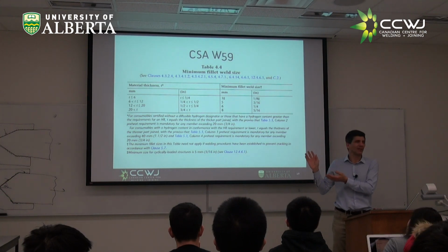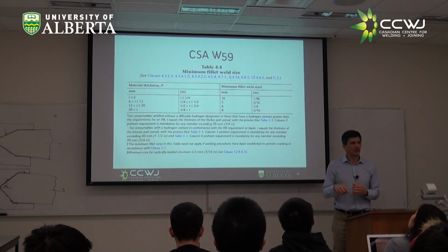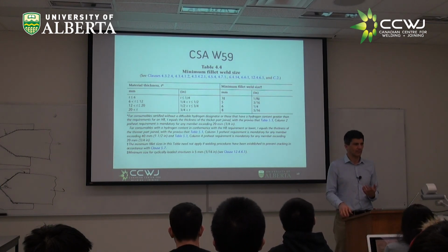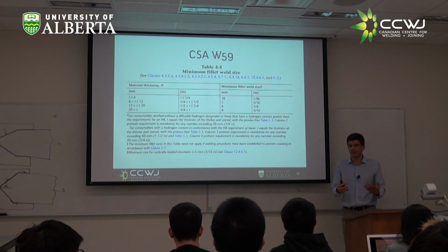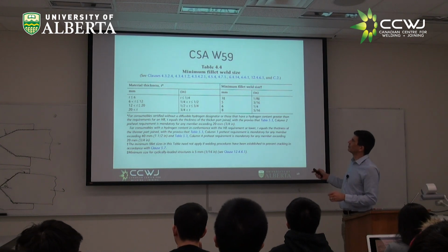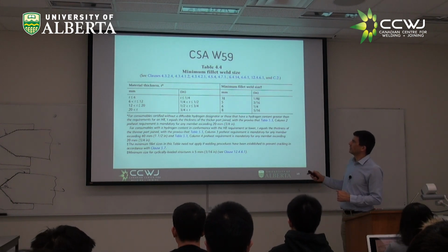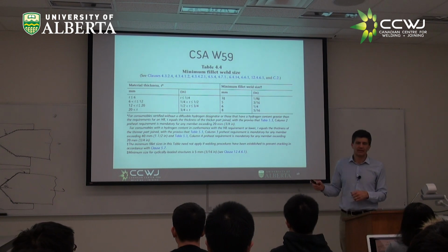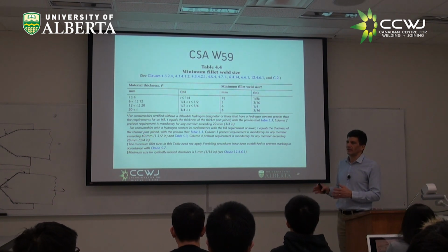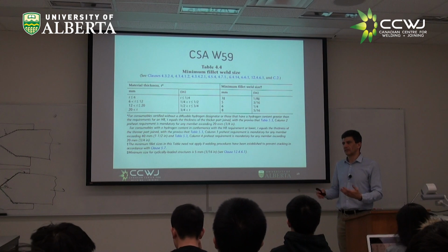If they don't say minimum weld, you can still break it, right? So if you have too small of a weld, the cooling rate is too high, and you might end up with cracking, right? Hydrogen cracking due to a hard microstructure. So for this reason, they say, okay, don't do single passes that are too small. And also, if you have a big plate, you can still make a 3 millimeter weld. That's okay. But if I have a plate that is too big, there is some kind of common sense in which the thing should be able to bear its own weight.